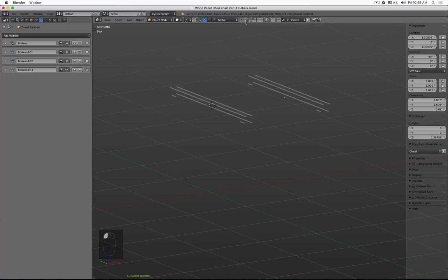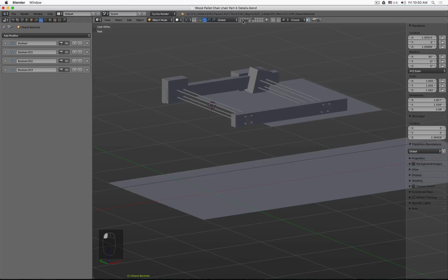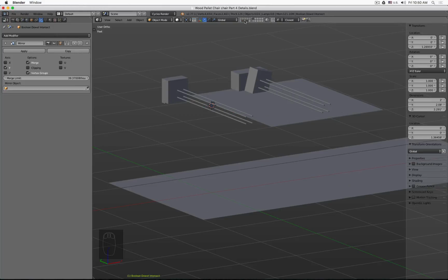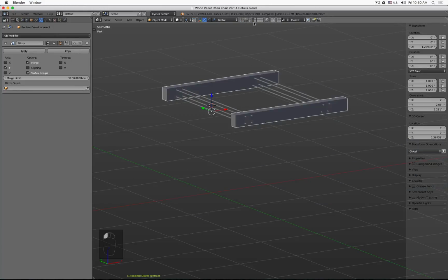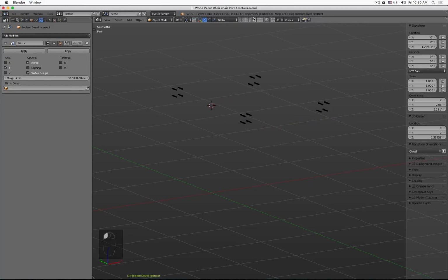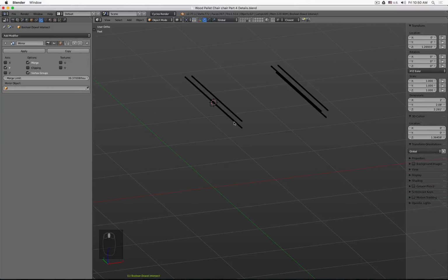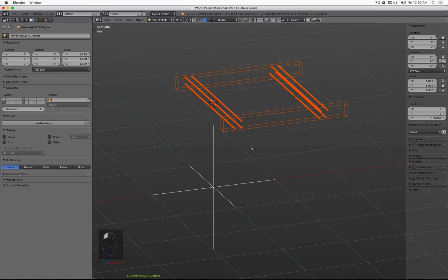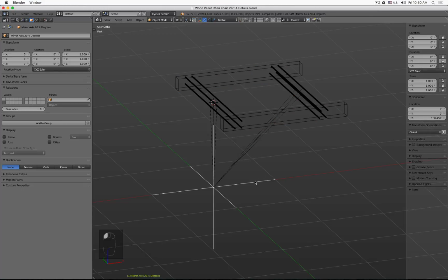Okay, before we continue, the last thing that's really important is actually to make sure that all those elements we created, so the dowels and then the Boolean shapes for the dowels, they're all linked to this one. Control P. So later when we rotate everything back, also the dowels will move with it.